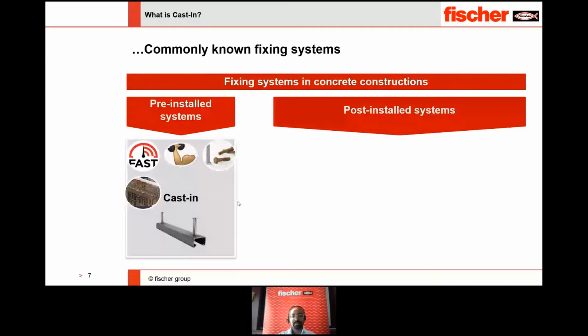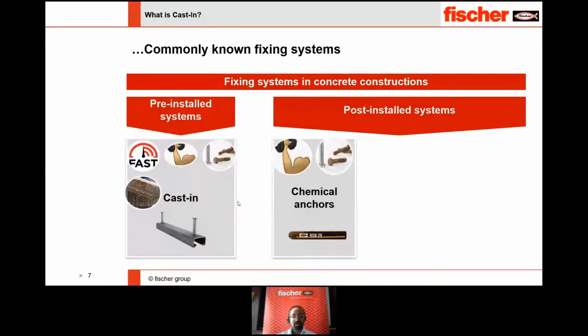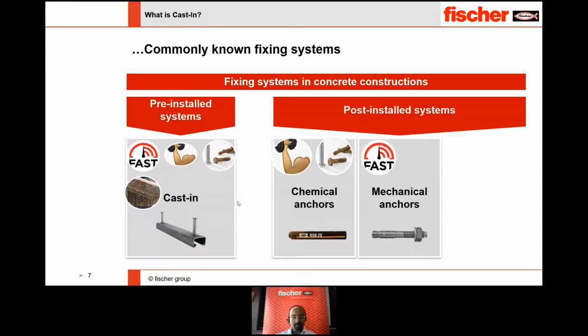The second system, the post-installed system, has mainly chemical anchors and mechanical anchors. Chemical anchors, we all know, are heavy duty and can stand corrosion, subject to the grade of material we carefully select. And then mechanical anchors are fast.